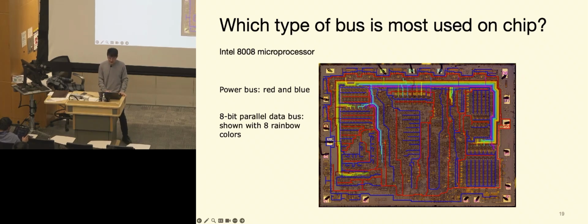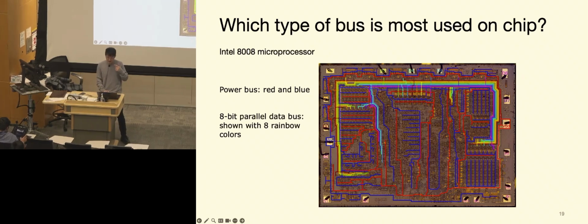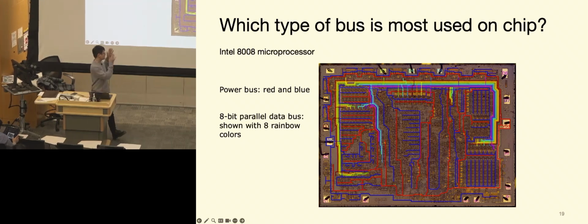The reason we need all those bus architectures is that a lot of components on the chip, even on the chip, are pretty far away from each other and all over the place. So we need those parallel high-speed communications to connect them all together for data sharing and data transportation.